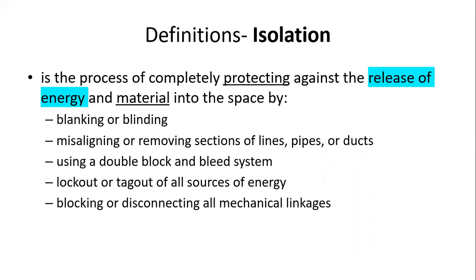Now, isolation. We had a slide before where we talked about blinding and blocking, and in some confined spaces there are things in there, pipelines, electrical lines, that could hurt us. So we have to figure out ways to isolate ourselves from those sources of energy and sometimes materials. For instance, it could be a very high pressure water main that if it broke, it would fill up the hole so quickly you couldn't even get out.